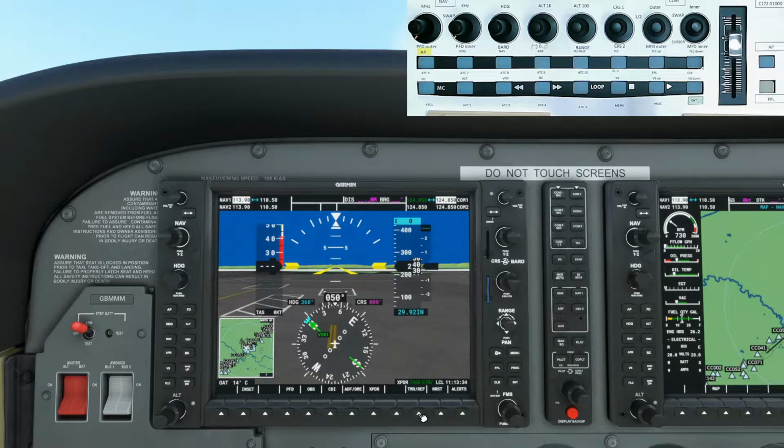What it has got of some interest to us is a timer. If you're flying old-fashioned navigation where you need to time your 2-minute turns or time your distance to travel, we have got a timer here, and we can also put various speed references onto the speed tape here. And I'm going to put VY, which is our best rate of climb, onto that tape, and they've calculated it at 74 knots. I came up with 76 knots when I did a previous video, and I programmed that in on here as my best rate of climb. So 74, 76, it's pretty close.